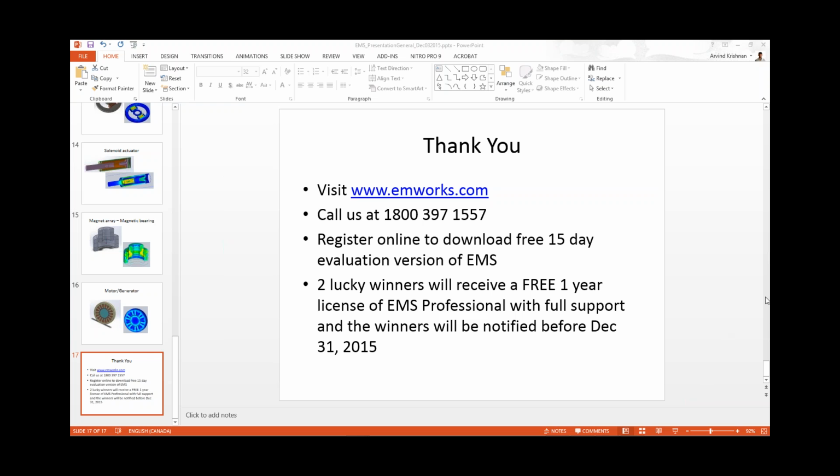There's another question, Arvind. The gentleman is saying, how does EMS behave in case of overlaps inside parts of a 3D model? Yeah, there cannot be any overlap inside the part for a 3D model. So EMS will not function if you have overlaps or interference between parts. You'll have to resolve them and make sure that there is no interference in your geometry before you run the simulation.